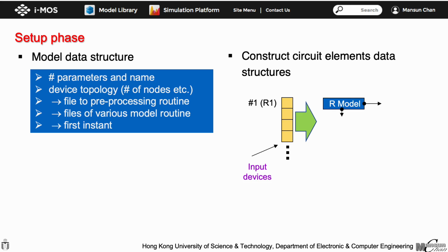For each device, the circuit simulator creates its associated model. The model class contains the class name and the parameters common to all devices belonging to the same model. All shared model parameters are processed here by the model-related subroutines. At the end, the model contains a pointer to the first instance data structure using this model.